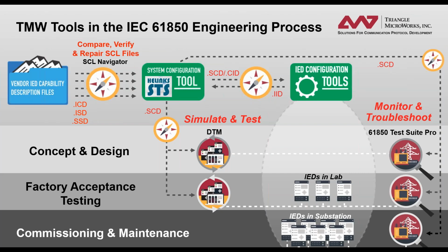Okay. Do we get SCL ICD files when we buy a device, or can we download them from the device itself? This depends on the vendor. Some vendors you can download the ICD files. That's mainly for devices that have not necessarily flexibility. If you have a multifunctional IED that you can configure with the vendor tool, whether it does what kind of protection functions it does, then you may create it with the vendor tool when you configure it to your specific purpose.